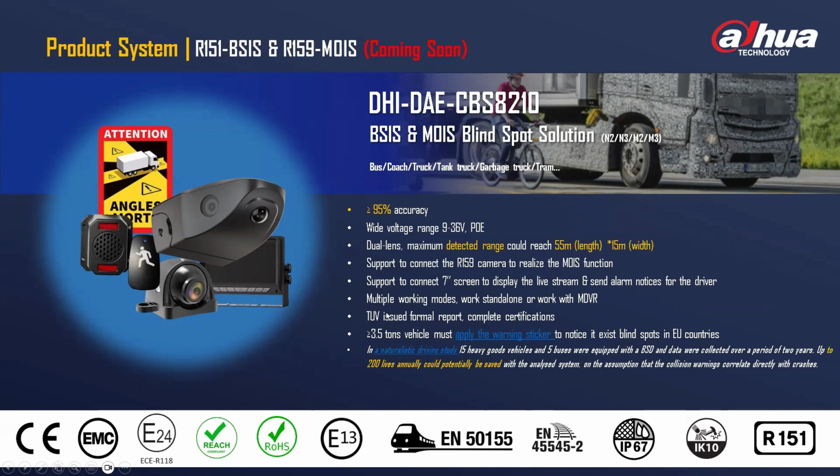The objective is, actually, before I proceed, I just want to highlight this camera is 9 to 36 volts, but all the mobile products I've highlighted usually work between 6 to 36 volts, which gives them optimized performance because in a vehicle the voltage fluctuation is usually very high, but we can use this to stabilize and sort out.